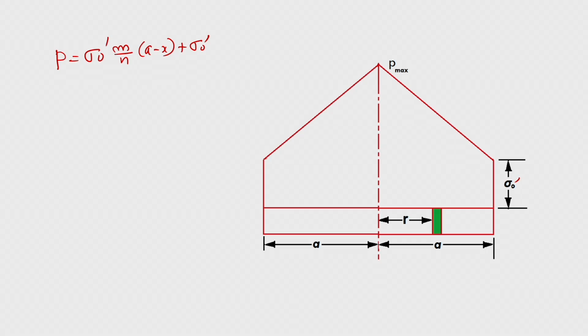So, that means there is a limit. Since the pressure distribution here is linear, in the actual case it will neither be perfectly sliding nor perfectly sticking. If it is perfect sliding, then m is equal to 0, where Coulomb's law of friction will be applicable.